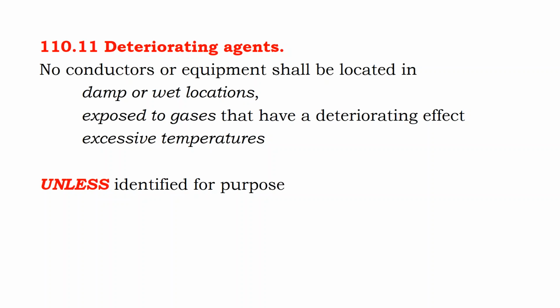Well, rather than getting too caught up in the technical side of it, let's take a step back. The rooftop is subject to extreme temperature. Out of every place on your building, the rooftop's going to be one of the hottest places. So should we be using wire that is rated for a higher 90 C environment on your rooftop? Yes, it's one of the hottest parts of the building. If you have the opportunity to use a better fit piece of material for that rooftop, then that's great. You want to use the 90 C wires on the rooftop.